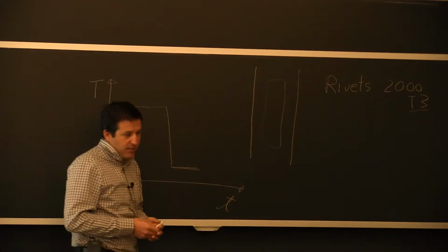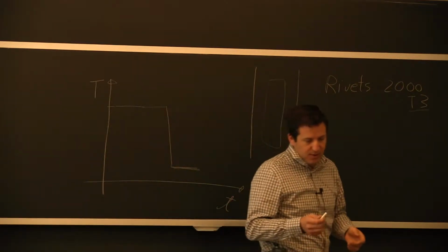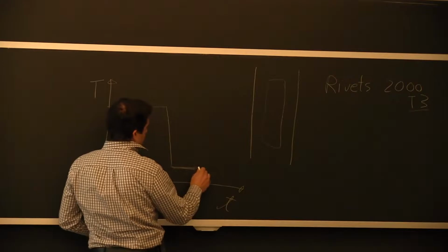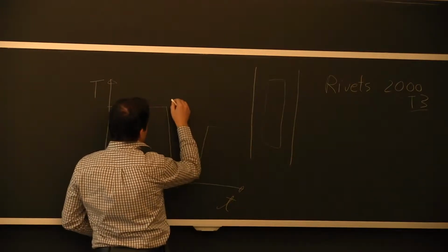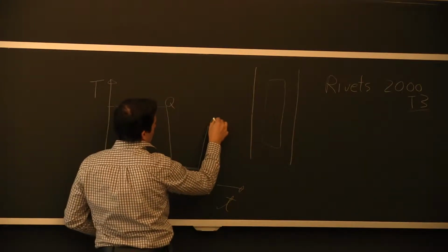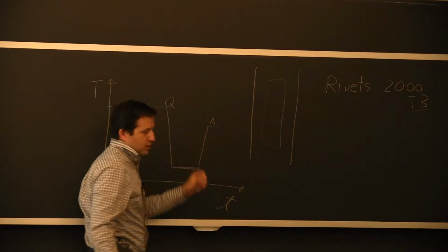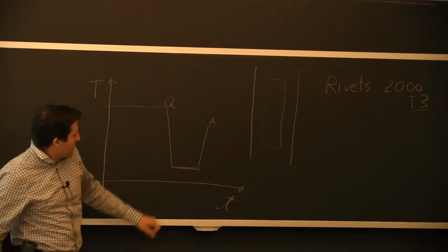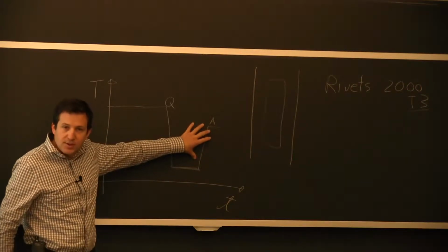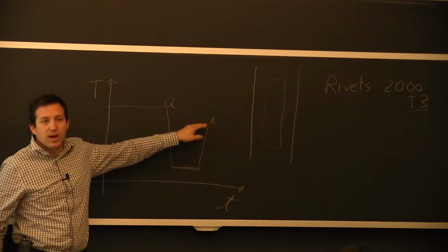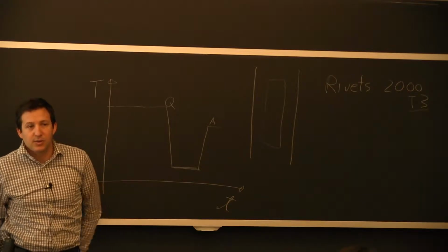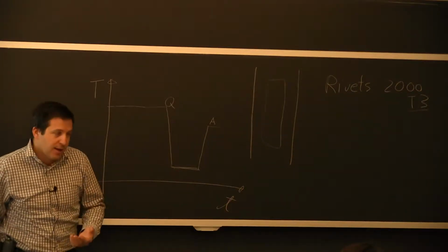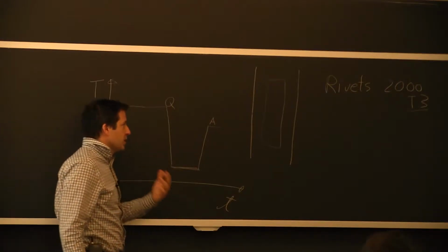A lot of alloys, the 6000 series, the 7000 series that Professor Eager mentioned yesterday, what you do is age them. So this was the quenching, and here we're going to age the microstructure. It's relatively low temperature, and that's why Professor Eager was saying sometimes in service, that aging process could be a cause for deterioration of properties, and that's if you over-age.